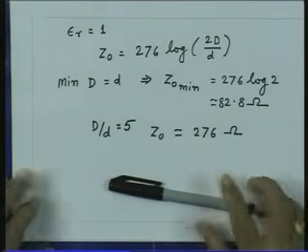So, the two structures, the coaxial cable structure and the parallel wire structure, are complementary in terms of characteristic impedance. The coaxial cable structure can give you low impedances rather easily, it is difficult to get high impedances, whereas if you go to the parallel wire line, then it is easier to realize the high characteristic impedance than the low characteristic impedance.